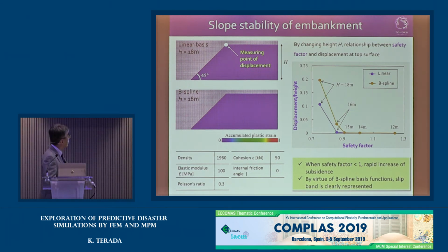At the same time, we can see here that the deformation with the linear basis function is not so appropriate like this, because we don't have a sharp profile of the slip line here. On the other hand, we could have the appropriate result with the B-spline function.